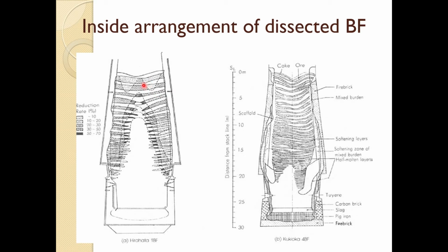So, alternate layers, they are coming, and you can see these are getting fused and narrow, the layers of raw material except the coke, and when it reaches this high temperature zone, your ore becomes semi molten in the region, or mushy zone, what you call it, but this white zone, the coke retains its structure. So, most of the gases then pass through this, because they cannot pass through the mushy zone due to very high resistance. So, there is a permeability issue here.